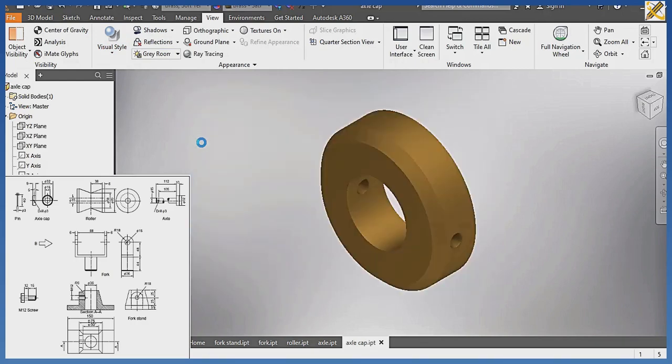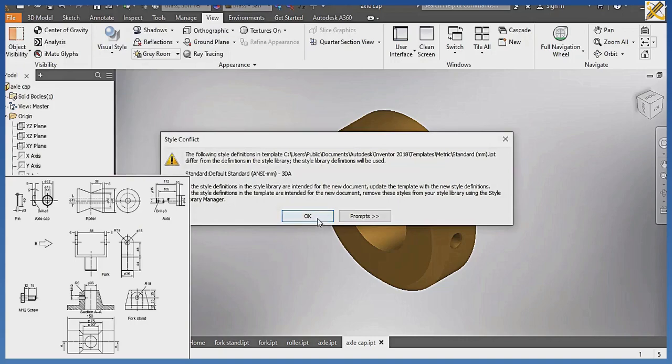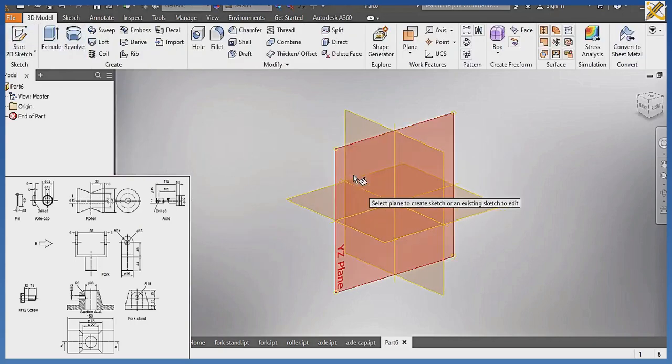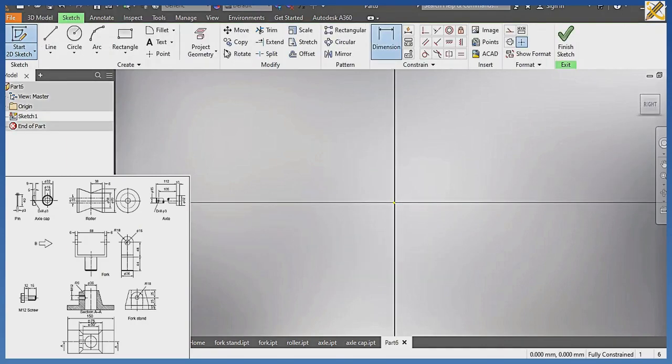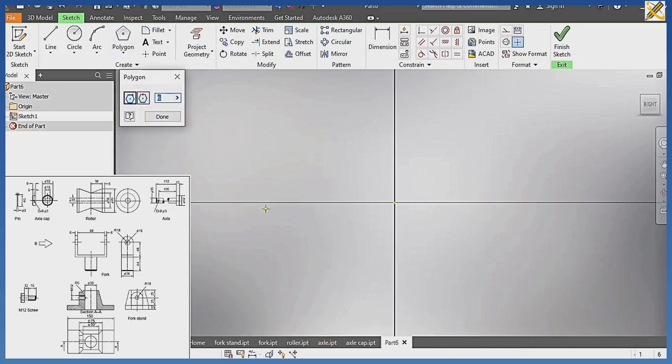Okay, now I'm going to produce my what, my M12 screw. So Control N, then what, create. Okay, so producing my M12 screw, I'm going to click on start to the sketch. I'm going to click on create sketch. Right here, I'm going to click on this. I'm going to pick my what, my polygon, with my polygon from this center. So take note, you see that the corner to corner of my polygon is still sitting on this center horizontal line. Okay, don't tilt it this way, let it sit like this so that you can dimension it what, easily.